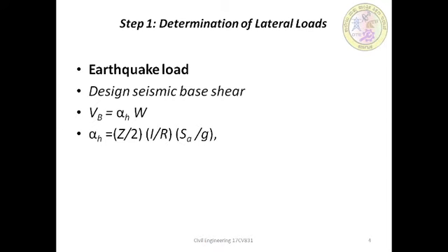The magnitude of lateral force mainly depends upon the seismic zone, type of soil, ground acceleration, ground conditions, and fundamental characteristics. The design base shear shall first be computed as a whole and then distributed along the height of the building based on simple formulas appropriate for buildings with regular distribution of mass and stiffnesses. The lateral force obtained at each floor level shall then be distributed to the individual lateral load resisting elements depending upon the floor diaphragm action.